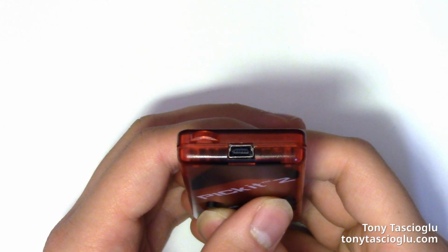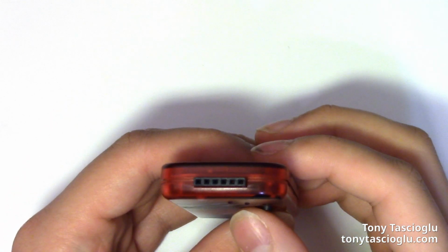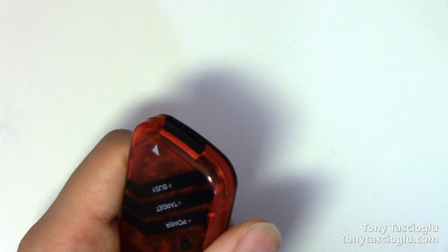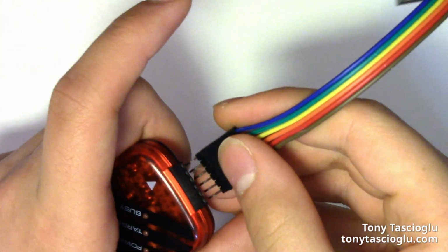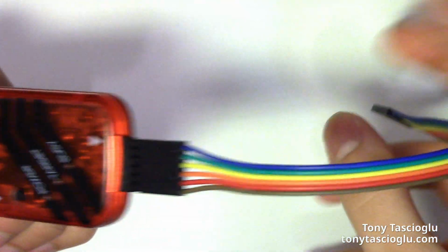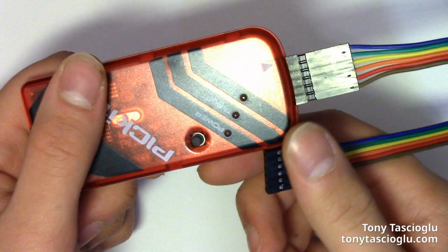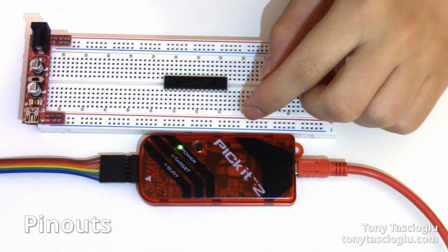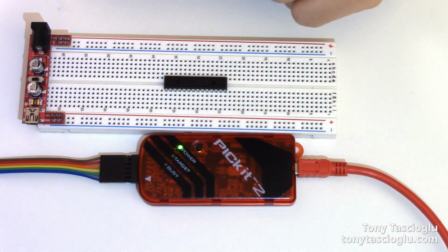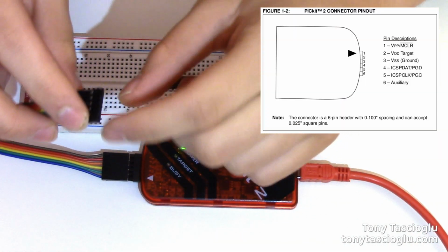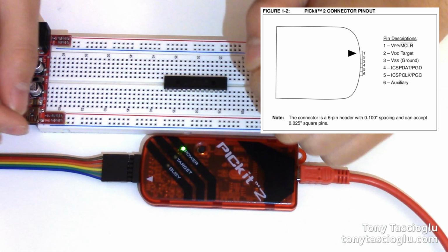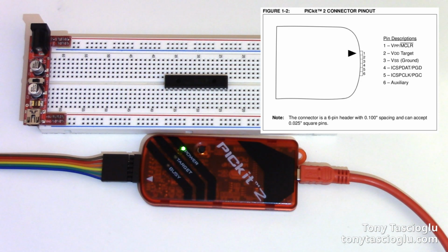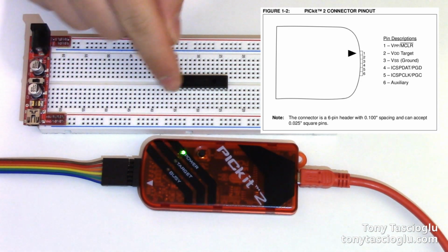On one end of the PICkit 2, we have a USB mini B port, and on the other end, we have the 6-pin connector. The 6-pin can be used with a simple ribbon cable to allow you to upload to multiple PIC devices. How these 6 will connect on your IC depends on the exact chip that you are following along with. So, to program this IC, we need to connect the output of the PICkit to the appropriate pins on the chip. The easiest way to do so is to just use some jumper wires from the output of the PICkit 2. The exact pins will change depending on which chip you're using, but you can just look at the pinout that is available for the PICkit 2 and for your IC.